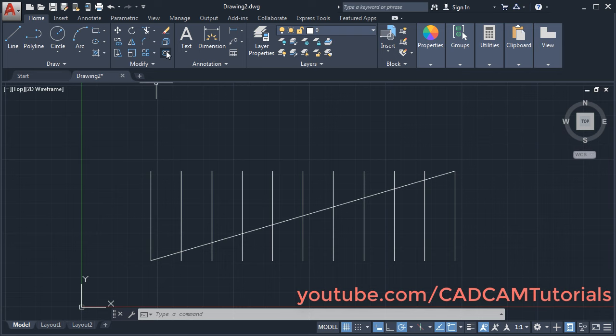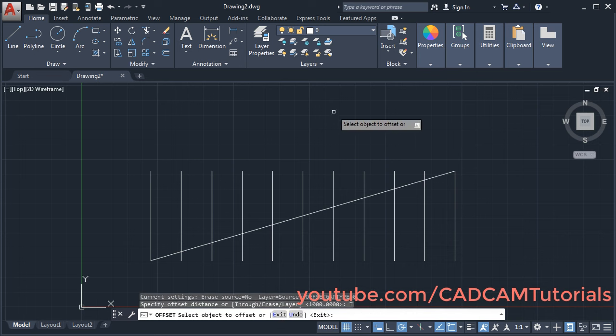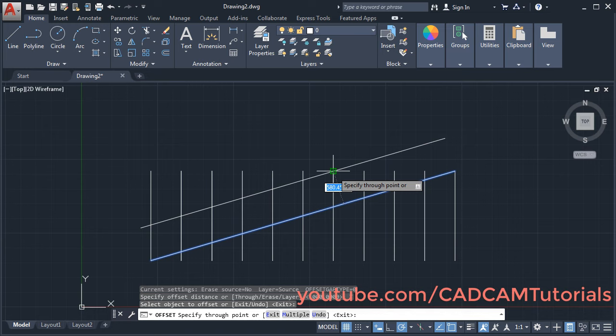For that, again click on offset. Then you will have to click on through. Then select the object to offset. Then you can specify the point. I want offset passing through this point, so just click on that point. So it will create offset passing through that point.